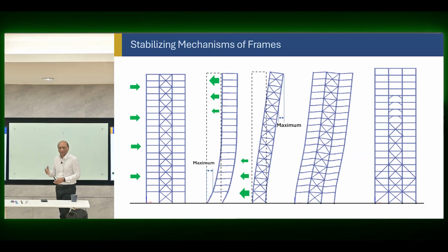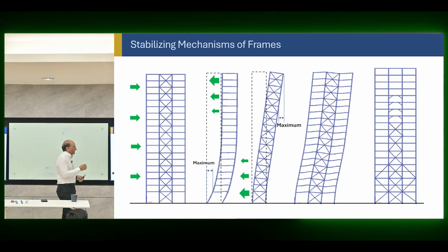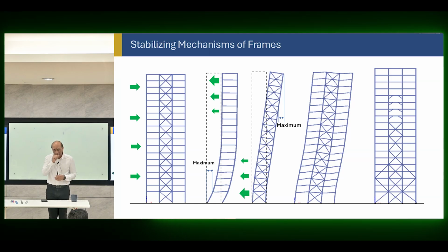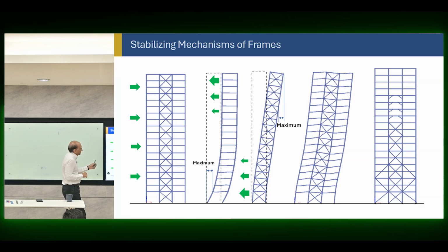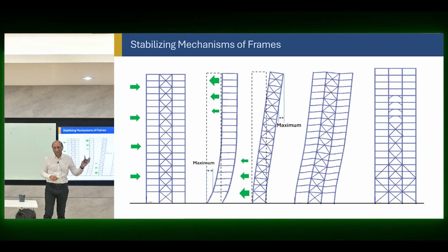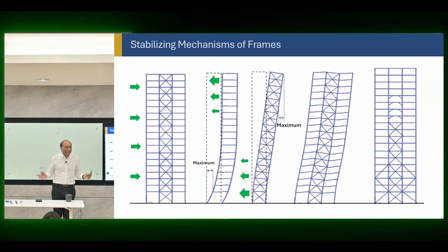Because if you overuse it, you get a displacement which is less. Nobody cares about less displacement because they want cost to be reduced. So a lot of the programs, a lot of the designs are drift optimized. There are software and procedures that optimize the structure for drift. Some structures are optimized for cost, some for natural period. But ultimately, for tall buildings, drift or displacement optimization is going to be the primary focus of our work. So any structural system that optimizes this will be very good.